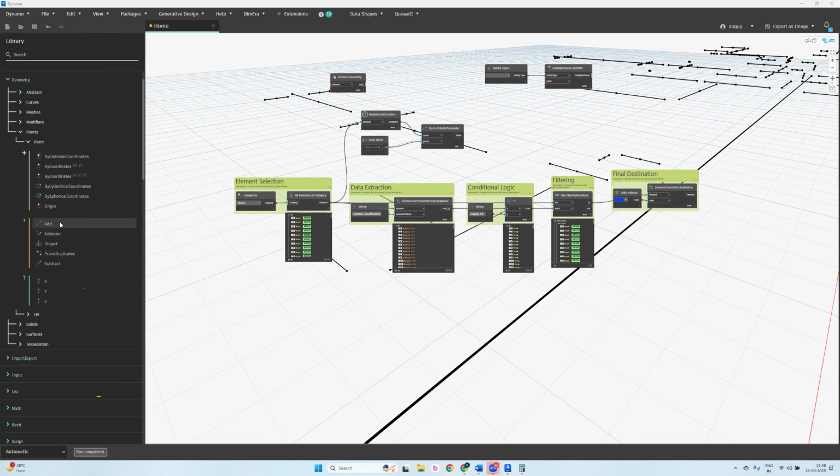You already have something and you want to move, delete, copy, duplicate or replicate it. You're playing with an existing object. These are called action nodes. Is it clear? Create nodes mean you are creating something which was not there before, and action nodes mean it's already there, but you want to move it in X, Y or Z direction, or duplicate, rotate or array it.